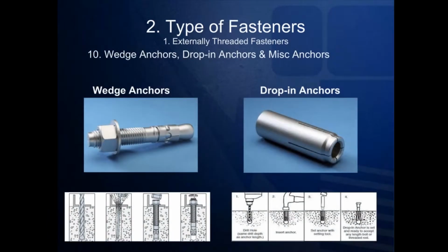Imagine having a piece of important machinery that is interconnected with other large, vibrating machines. I'm sure we'd all agree that you wouldn't want these machines to start vibrating and moving across the floor of the warehouse. For this reason, you would want to anchor them to the concrete foundation below them. Before you are two of the most common methods to anchor equipment and machinery to pre-existing concrete foundations. Common applications include anchoring pallet racks to the concrete floor to keep them from turning over, and also hanging pipe or hardware onto ceilings in parking garages using threaded rod and pipe hangers.